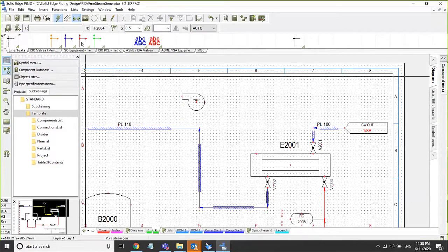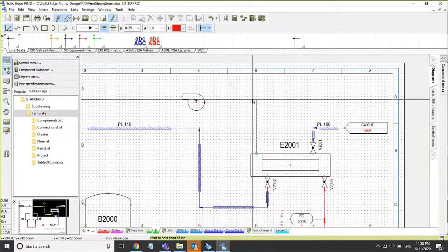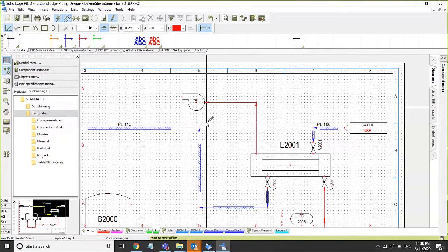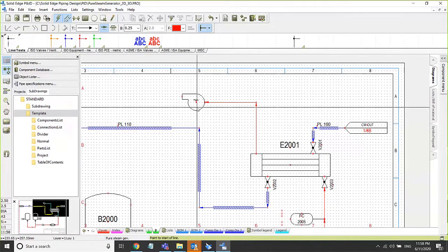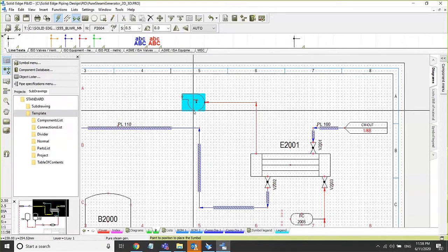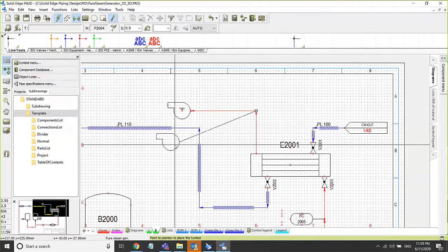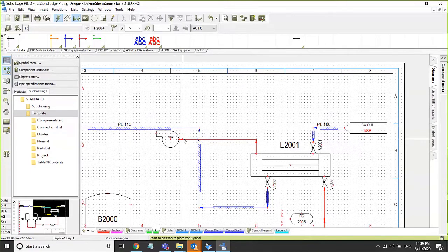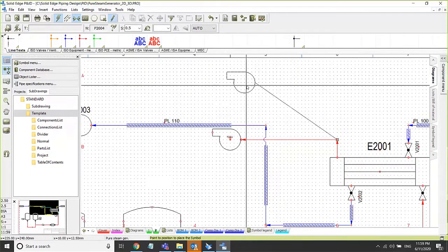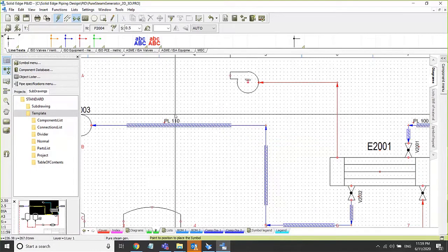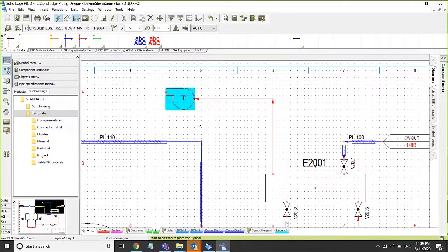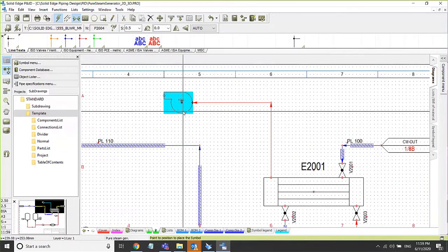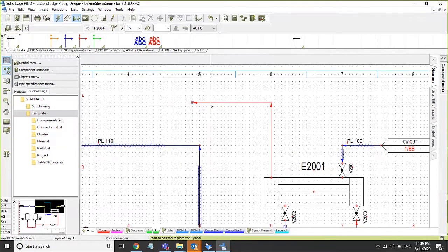So as I defined by placing a pump symbol, the next thing we would like to do is define a pipeline connection from one of the components, in this case from the heat exchanger to one end of the pump. So as you create the pipeline connections, it basically creates a dynamic link wherein as you move the symbol, the pipeline remains associative, even in case there are some intersections, it is going to update accordingly. So this is a use case wherein in the concept stage you can start placing the symbol, and later you can assign the components to that symbol.